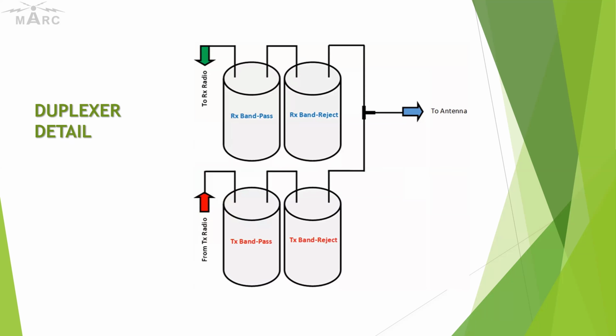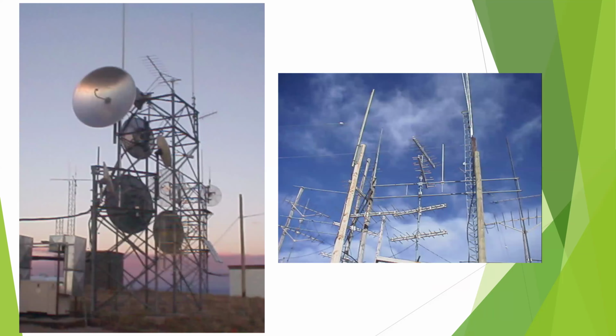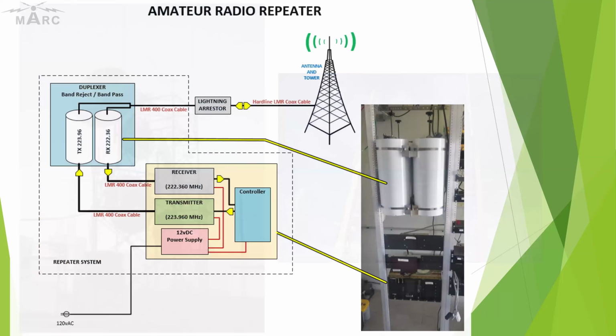Physically, how are they made? I know they're filters, I understand electronic filtering circuits, but physically, what's inside the can? These cans are actually quarter wave antennas. Okay, so we have 4 of them there. We have an entire wavelength of our repeater frequency, and most of it is hollow.